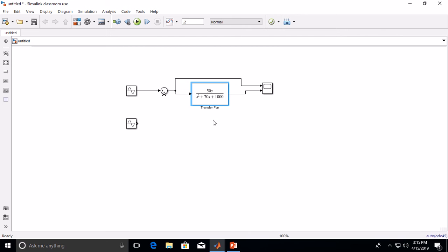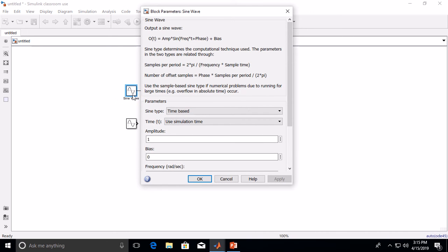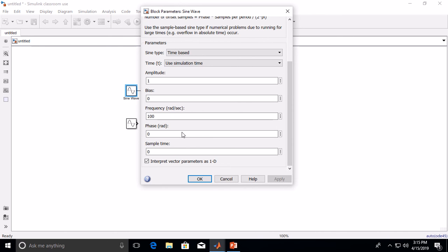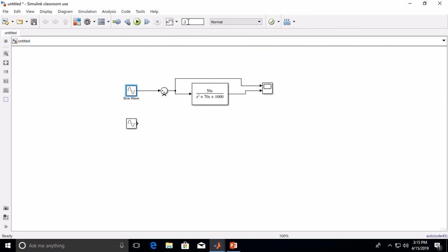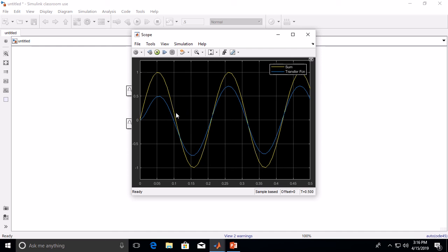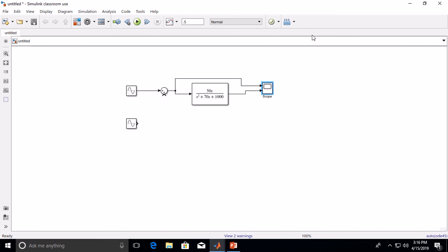And then we're going to run just a few tests with this, with a few different inputs just to show what it's like. From that, the band pass is actually from 20 radians per second to 50 radians per second. So we're actually just going to go in the middle there, let's do 30. Let's do 0.5. Let's run that. And because it's in the middle, it will pass through at about an amplitude of 0.5.